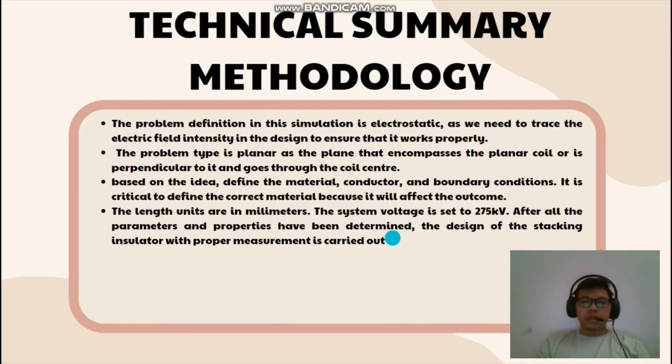Next is the technical summary, methodology. The problem definition in the simulation is an electrostatic problem, as we need to trace the electric field intensity in the design to ensure that it works properly. Next, the problem type is planar, as the plane that encompasses the planar coil or is perpendicular to it and goes through the coil center.